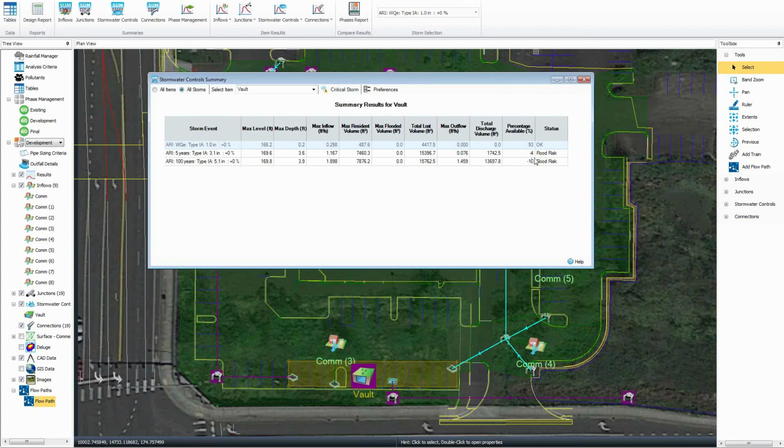Okay, so this starts counting at your freeboard elevation, and you can see over here we're at 3.9 feet of water depth. Well, our facility is 4 feet deep, so we're just towards the top. So this is actually okay. This is great. And that's one thing I use the freeboard for, is to really let myself know how close we're getting to the top.